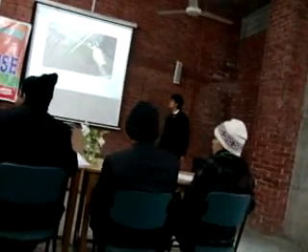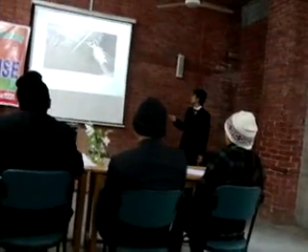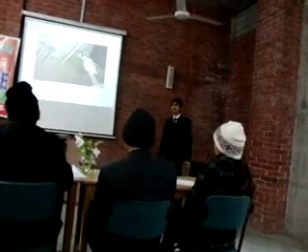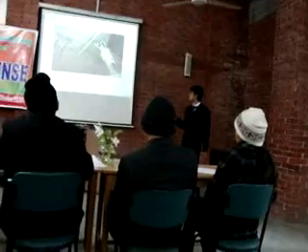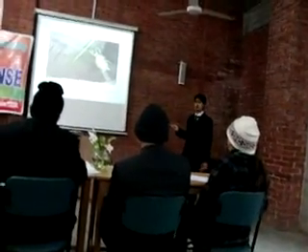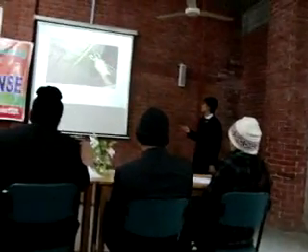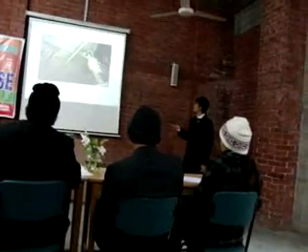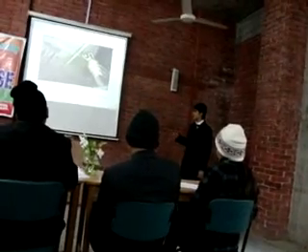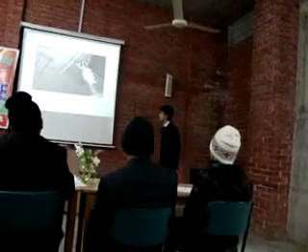This is the sensor connection. Here you can see the hydrostatic sensor and water level sensor. These sensors are directly connected to the input module. The sensors send different types of signals. The signal range is 4 milliampere to 20 milliampere, representing different conditions of water level. There is the vat, and this vat holds water. This sensor is sensing the different conditions of the water and sends the signal to the PLC.